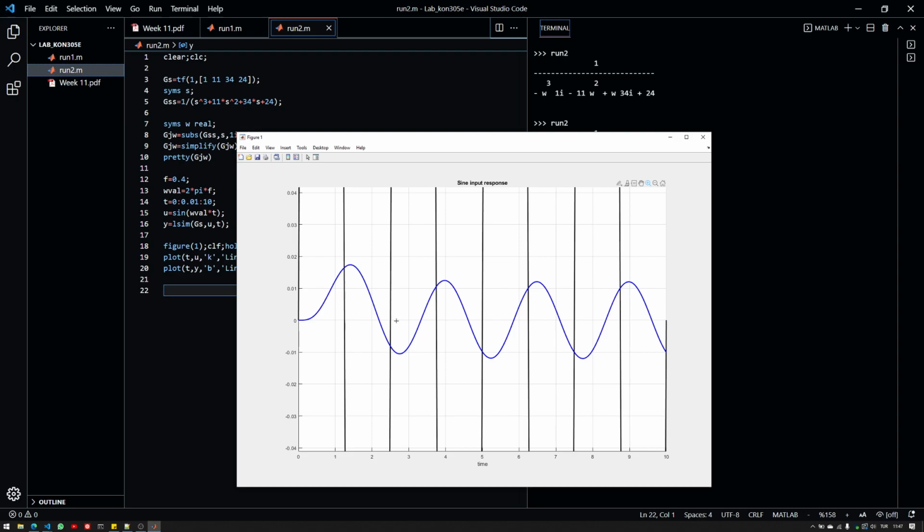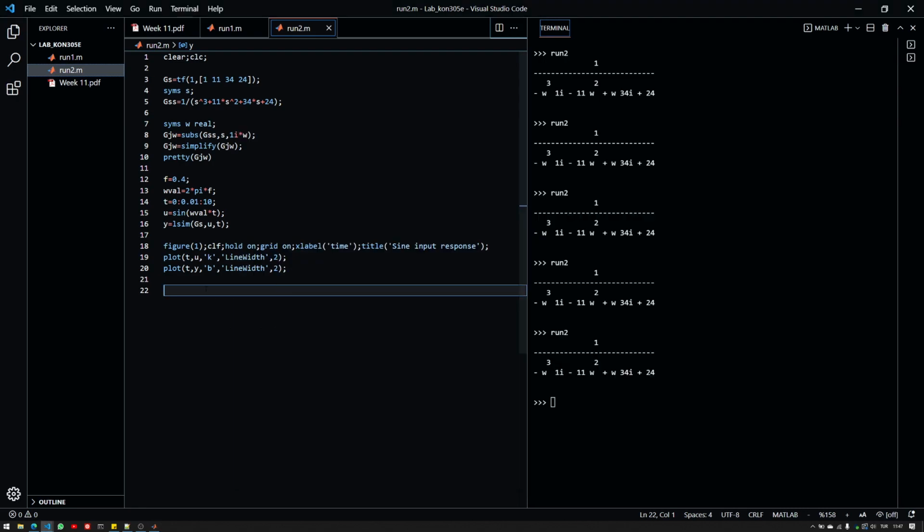Only then the frequency can change. So this means that the frequency should really not change. If I have a certain frequency in my input, the output should have the same frequency. The only thing that can change for sine waves, in this case, is the gain and the phase, not the frequency. So the sine wave should have the same frequency, but a little phase shift. So, yeah. How can I calculate this?